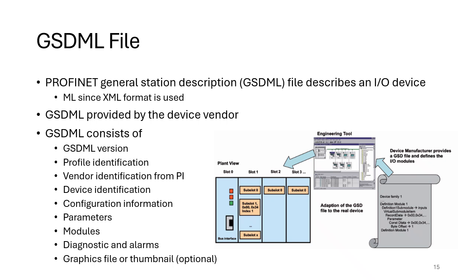The important thing is, wherever possible, make sure you've got the latest GSDML file and make sure you've got the correct GSDML file. I've seen some vendors who get a bit confused and they'll send you the wrong GSDML file. If things don't work, that's one thing to check alongside all of your standard configuration and diagnostics, like is the device actually there, what do the LEDs say, and so on. Make sure you've got the right GSDML file, because if that doesn't match the device will just not work.